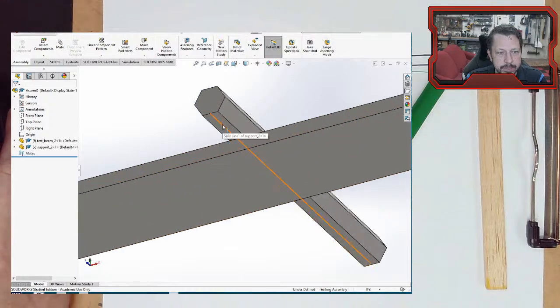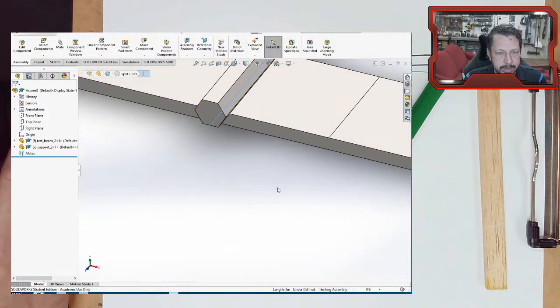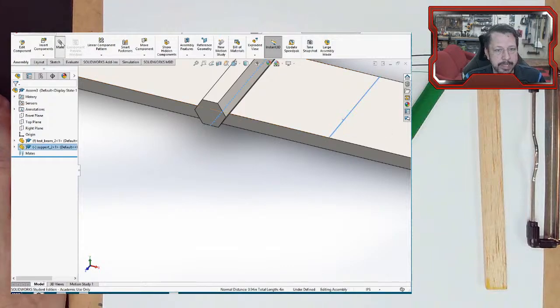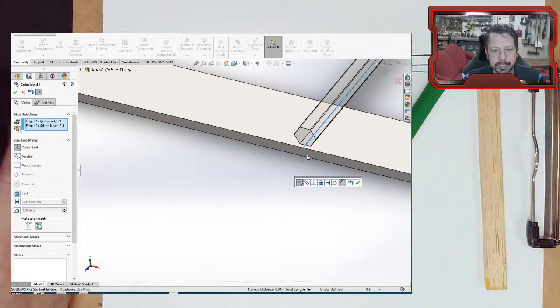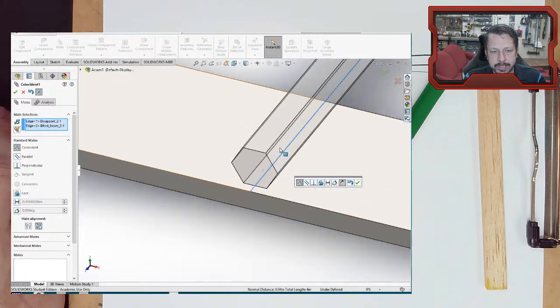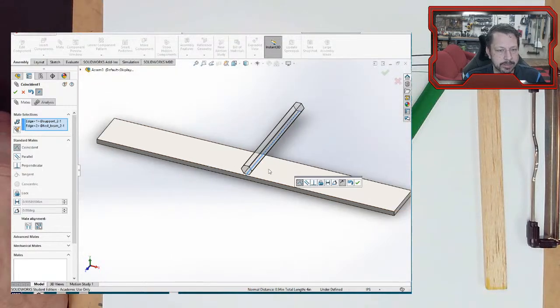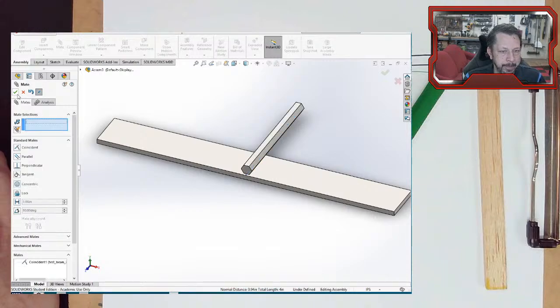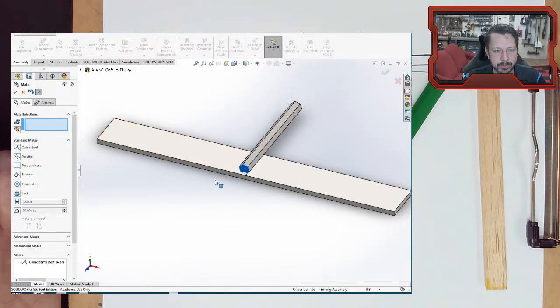So here's what I'm going to use, that split line lined up with that split line. And I will mate those together so that way it's definitely in the center. It's a little bit difficult to figure out how far over to set because I can't click just the center of this face. So that's why I made that split line. I don't want it sitting over here though. I want it, you know, where do I move it? Oh wow, I didn't want to tilt the thing though.